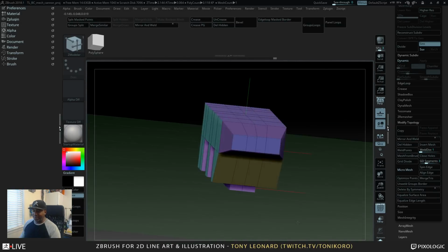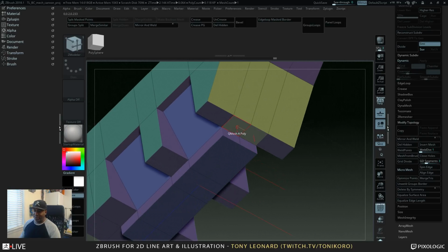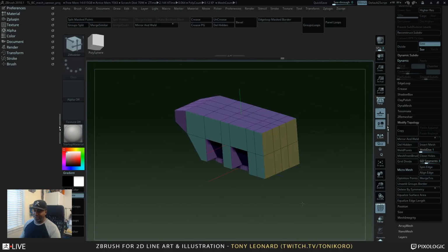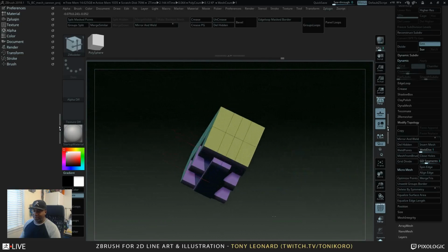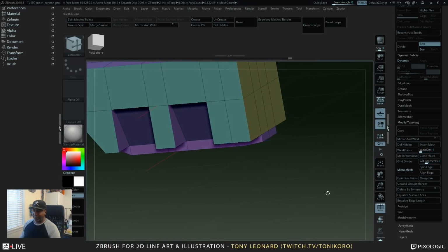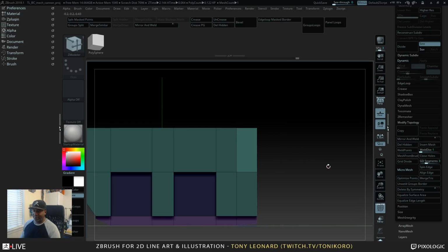So this looks kind of blocky right now, but what I can do is go in and select other faces, pull on them in the same half step, create an angle, and everything is still quads, which is really nice to work with simplistically in this way. So there, I start to think of the shapes a little bit more. So I'm going to hit this and mask it, invert it, get the move tool out again, rearrange that over here, and pull this down.